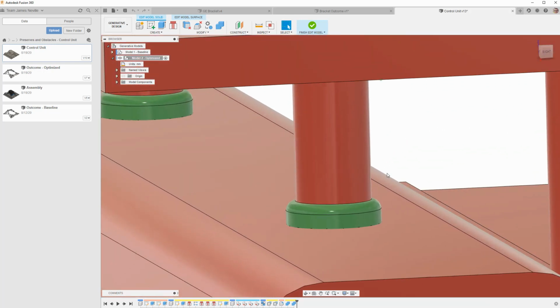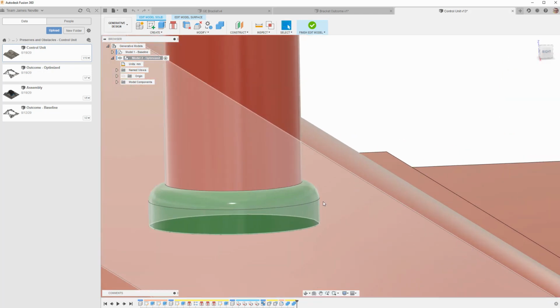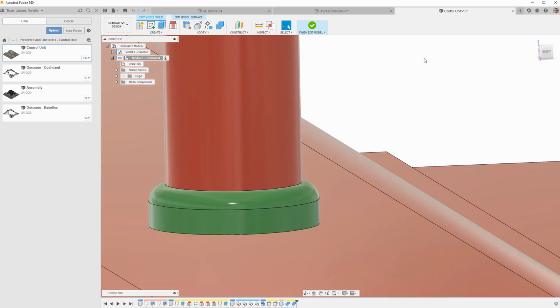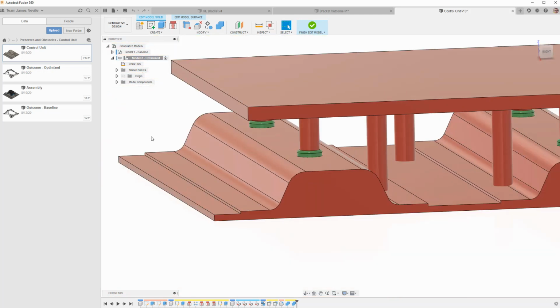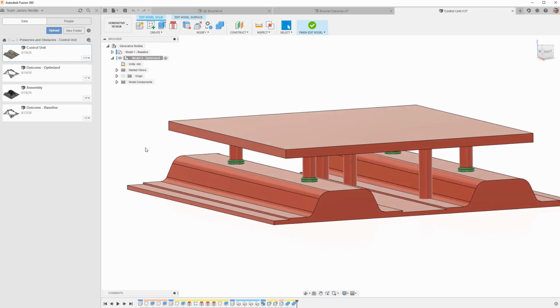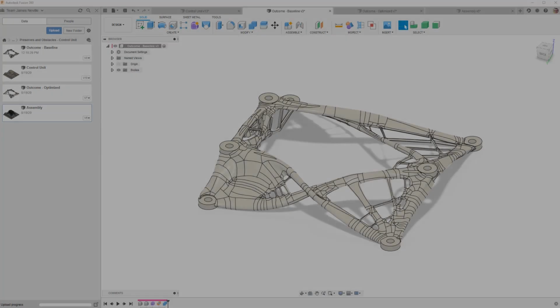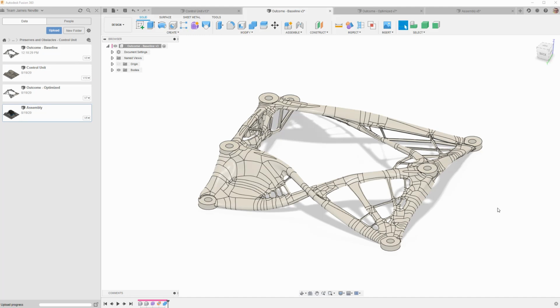You can also see that I've made some changes to the preserve itself. I've rounded this top surface. Basically, the landing zone, the area where the generative form shape is going to come down and build to, is always curved here. There's no sharp edge. That's going to make adding a stress relief fillet afterwards very, very easy. And this is just a tip and trick for getting a slightly more optimized generative outcome at the setup stage, as opposed to doing this all at the post processing stage, if you will.